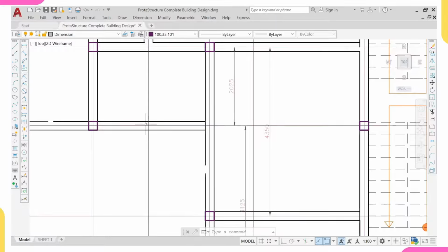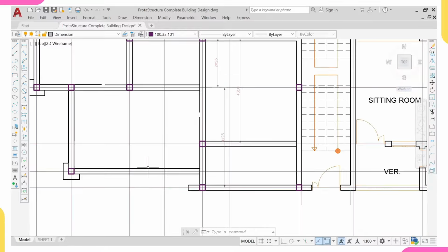So this beam now will not share its load between this and this. That means it's half of the load that is coming to this beam. I don't know if they understand it, but this beam now is too long, so the load coming from this will be more than the load coming from this, even though they are in two directions. But this one is a very long beam, and two, this is a very big slab panel.